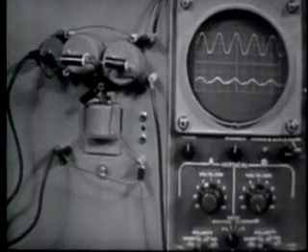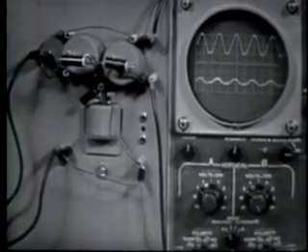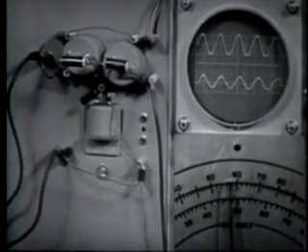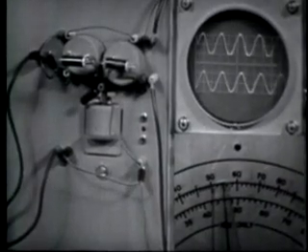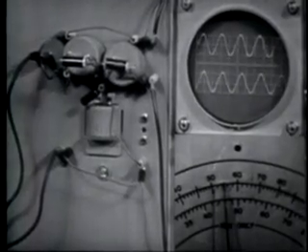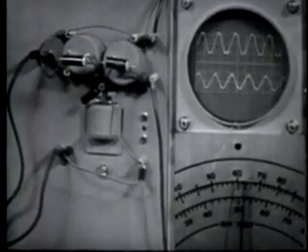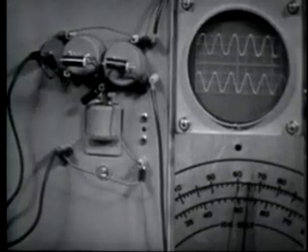Now let's check the frequency response of this circuit and see if we have indeed improved it. All right. Notice now that I only have to go down to about 550 hertz and I have maximum output from the filter. The same is true on the other side of the frequency we wish to reject. At about 650 hertz I now have maximum output from the filter.